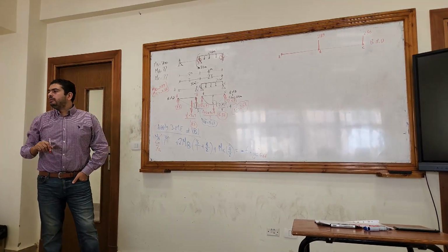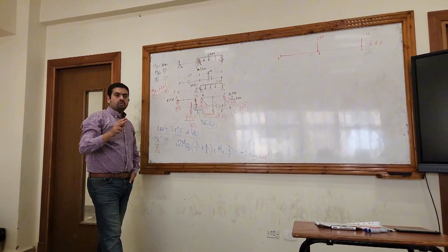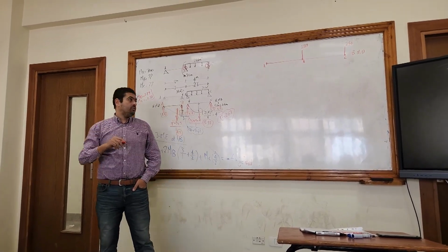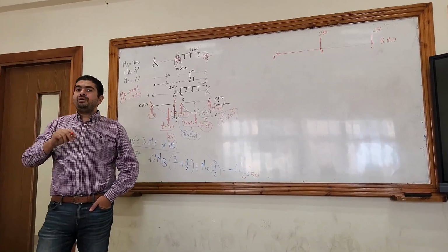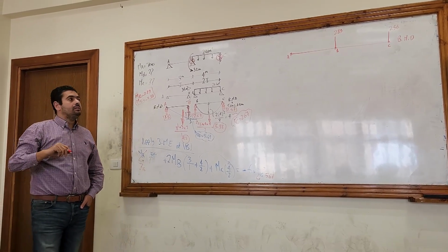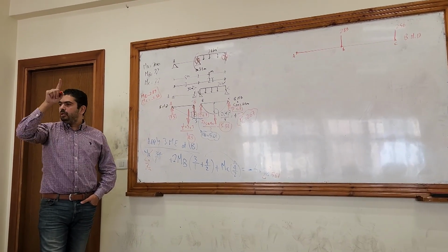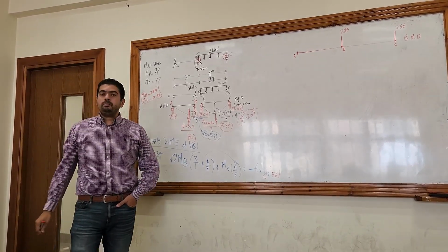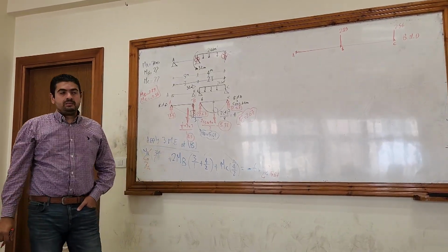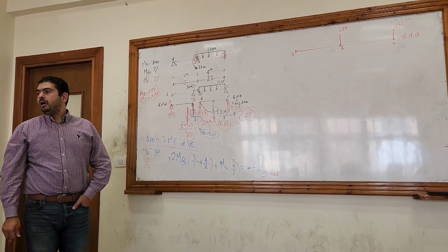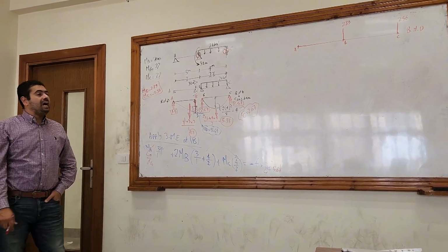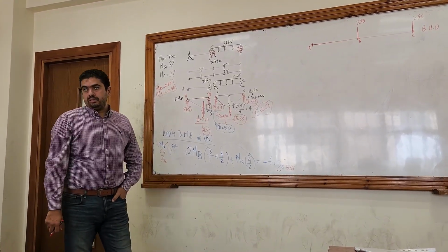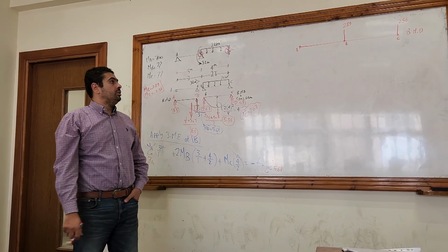I have to calculate the moment 2 times, right and left, and I have to put the two values on the bending moment diagram, and there's a drop in the bending moment diagram when there is a concentrated moment. So the question is, the 2.89, is it MB right or MB left? This is the main question now.